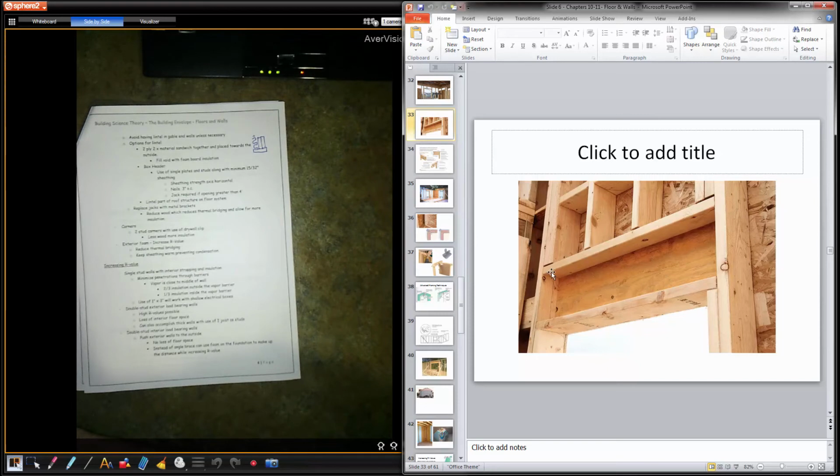So cut that out. There's a cripple here that does not need to be here. There's a double here. I don't think that piece needs to be here. Again, another double here. I don't think that piece needs to be here. Just a bad habit of somebody putting a 2x4 to support a rough sill. The blocking here is more likely required. The wall's balloon framed.